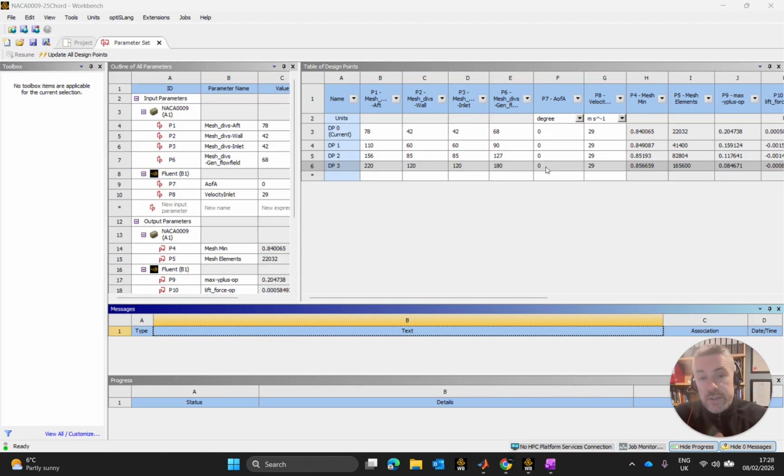We have compared the NACA 0009 and now it's time to compare other airfoils against it and see how it stacks up. We have to be sure that we're also going to use the same input parameters, so we are comparing like for like. Our angle of attack obviously is going to stay at 0 degrees. Our velocity we're going to keep the same from airfoil to airfoil, and as I said, we'll ensure that we're laying it down on the same discretized domain.